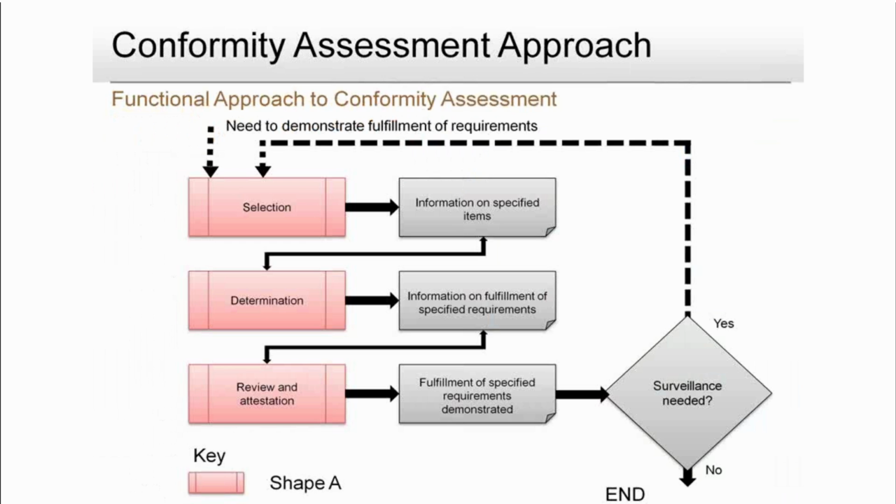Equipment, that's clause 5.5. The equipment in use. Calibrate equipment when due, and keep record of calibration. I'll just take this item very briefly. I talked earlier about the calibration slip, and then also calibration certificate.